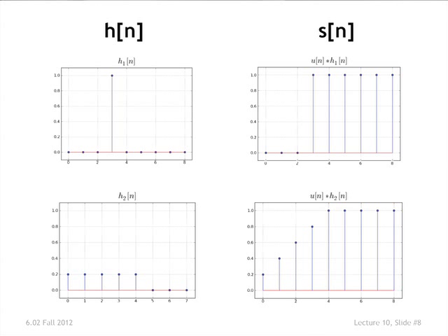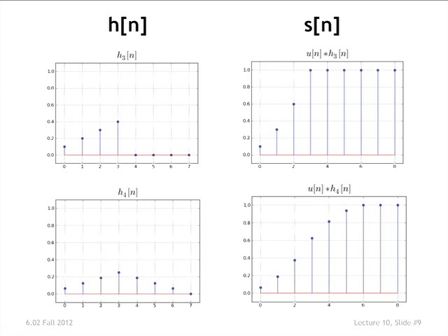I'm going a little slow here because we miss a recitation tomorrow. Recitations tomorrow are office hours, so I wanted to actually give you a few examples. Here's a case where the unit sample response increases linearly and then stops. And so the unit step response starts to accelerate quadratically and then stops. Okay, this is the discrete time version of integration that we're looking at.